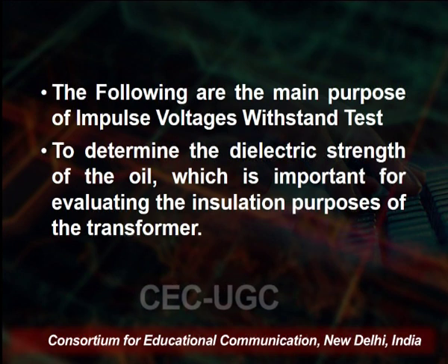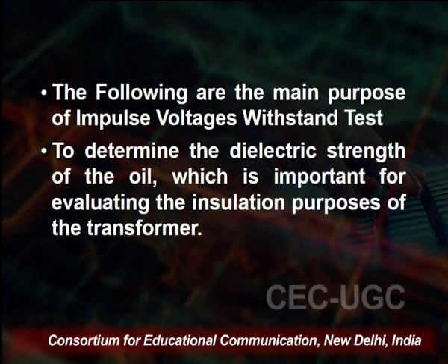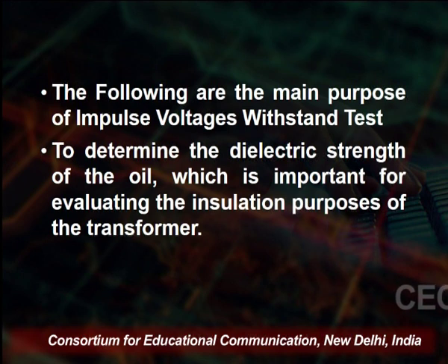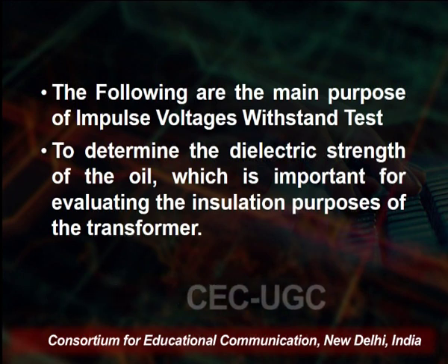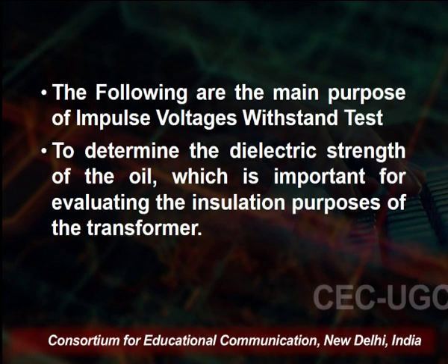Over time the quality of the oil degrades due to various factors such as moisture, oxidation and contamination, which results in reducing the efficiency and reliability of the transformer. The following are the main purposes of the test. First, to check the dielectric strength of the oil, which is important for evaluating the insulation performance of the transformer.